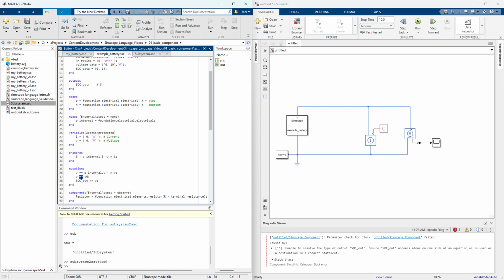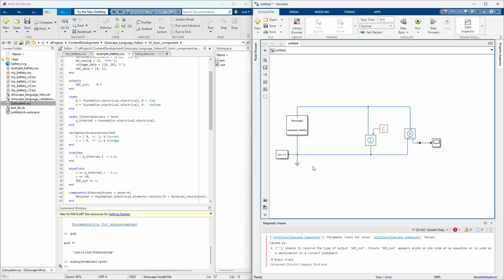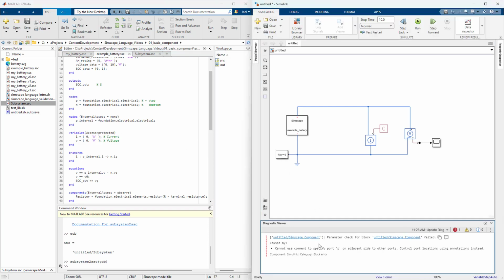I guess I didn't mention, when you're doing equations, you do equals equals, because it's not saying V naught is assigned to V. It's saying there's a relationship where V and V naught are equal to each other. So the single equals is an assignment operator, and an equal equals is a relationship operator. So that will get relevant.